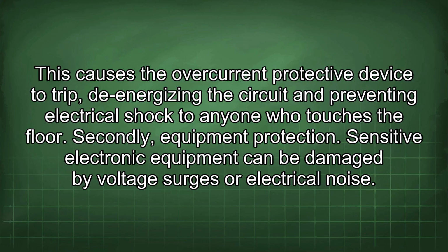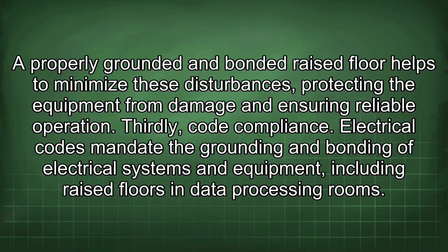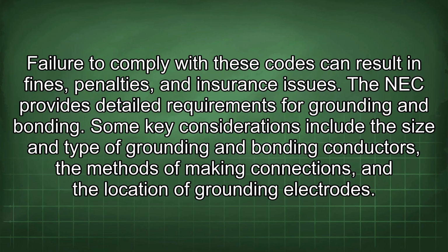Secondly, equipment protection. Sensitive electronic equipment can be damaged by voltage surges or electrical noise. A properly grounded and bonded raised floor helps to minimize these disturbances, protecting the equipment from damage and ensuring reliable operation. Thirdly, code compliance. Electrical codes mandate the grounding and bonding of electrical systems and equipment, including raised floors in data processing rooms. Failure to comply with these codes can result in fines, penalties, and insurance issues.